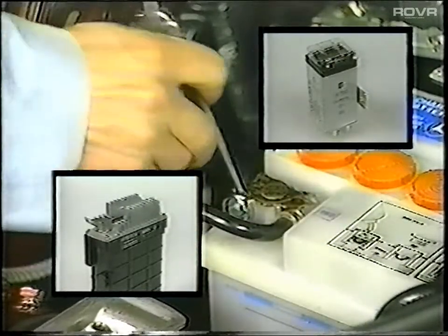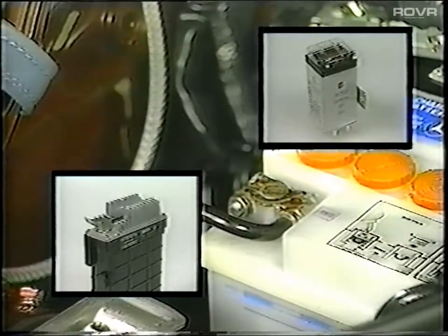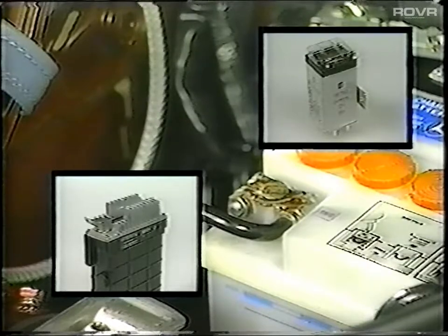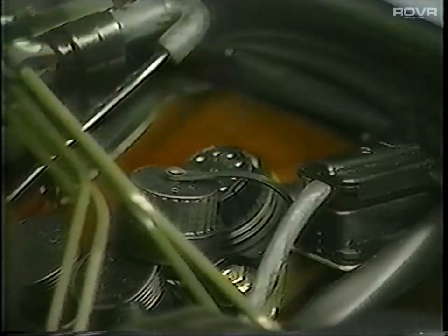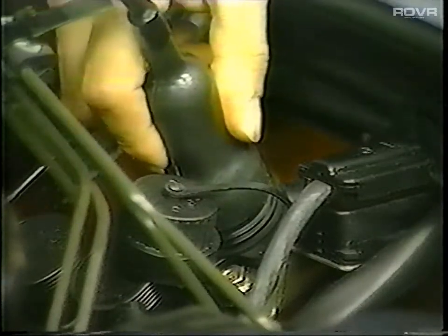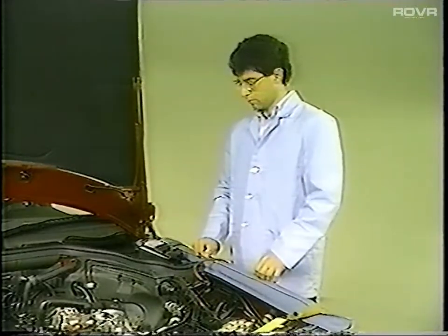And conversely, if repairs are completed without disconnecting a power supply, the memory must then be erased by disconnecting the battery for at least 5 seconds. On California vehicles, you should also refer to Test B in the introduction manual before attempting to check the adjustment of the on-off ratio for lambda control.